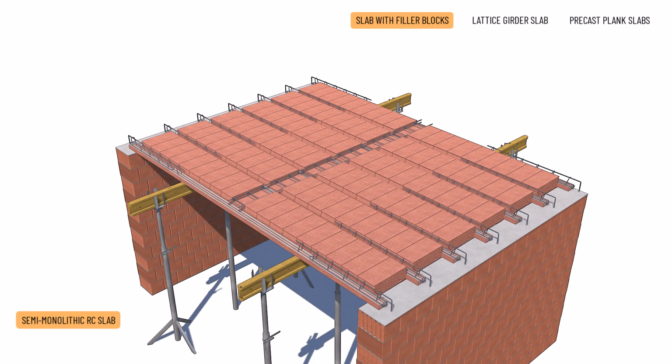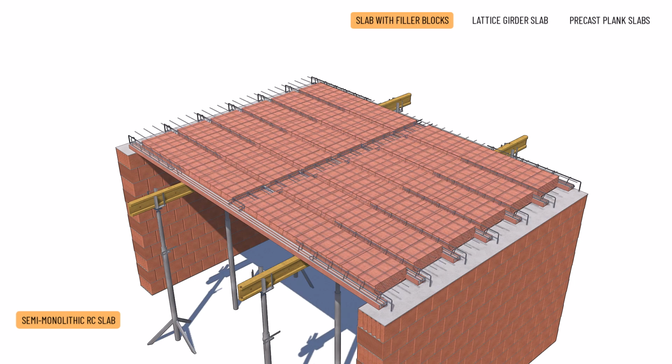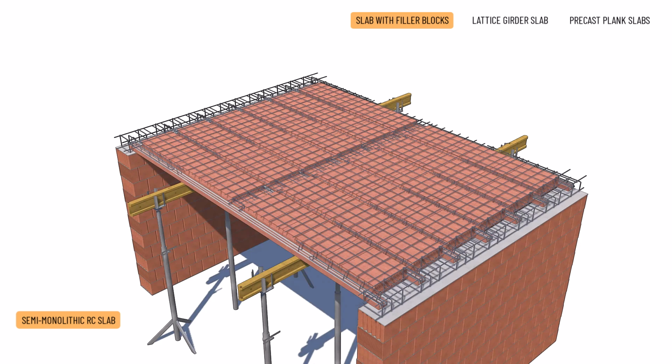A reinforcement mesh of 150 by 150 millimeter spacing and 6 millimeter diameter is placed to form the top concrete layer of the floor. The ring beam, cross beams, the monolithic reinforced concrete top layer, and the monolithic parts of the beams are poured all at once.